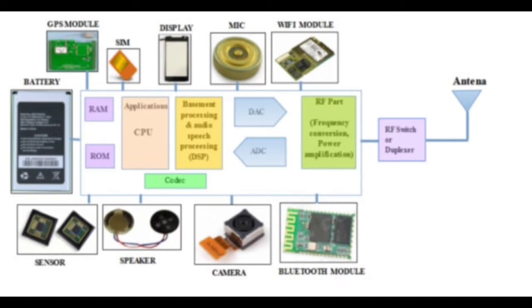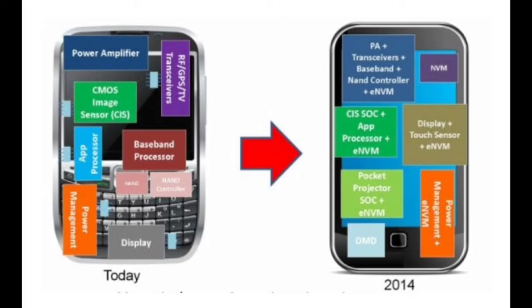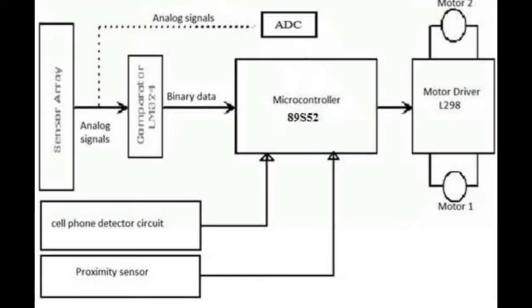Typically, a mobile phone will have a display, LCD touchscreen, keypad, microphone, speaker, SIM card, battery, USB port, antenna, memory unit, RAM and ROM, camera, codec, RF part, ADC and DAC, baseband part, which is L1, layer 1, physical layer, running on DSP, application protocol layers running on CPU, on-off switch, and Bluetooth and GPS features. All these features are based on specific standard specification design, like it may be based on GSM, WCDMA, or LTE.